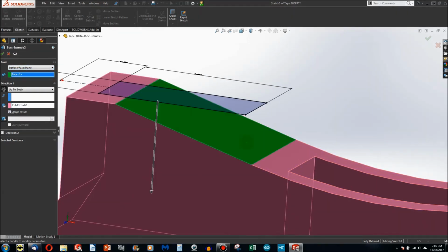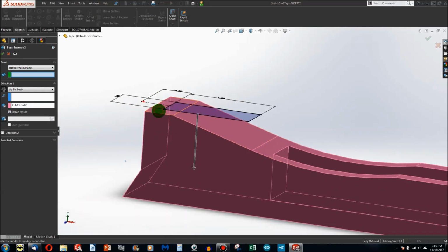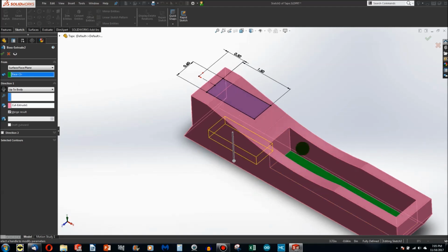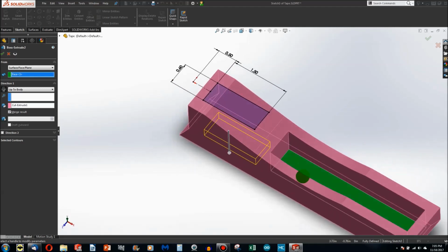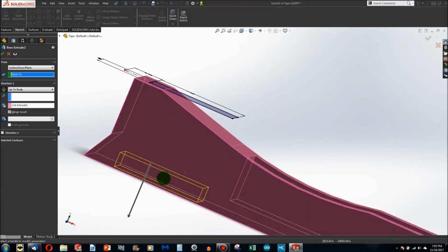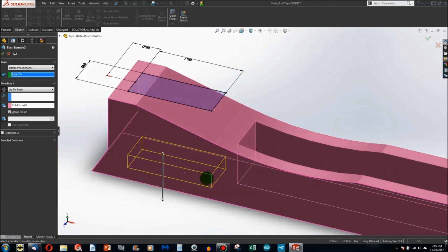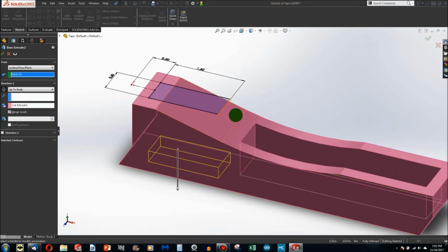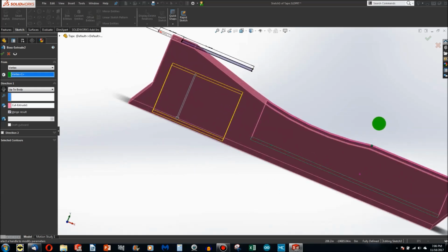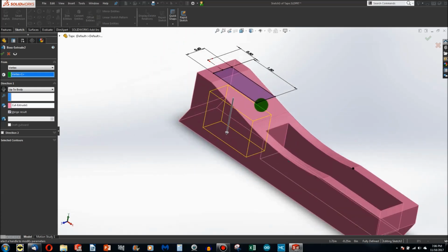I can also extrude from a surface. So if I choose this surface, then it will move the sketch onto this bottom surface and extrude from there. It's kind of a more simple way of saying offset, because I can choose the surface that I want to offset onto instead of calculating out a distance. Vertex is the same thing. Remember, vertexes are more like edges, so I can choose the height of that edge to extrude from.